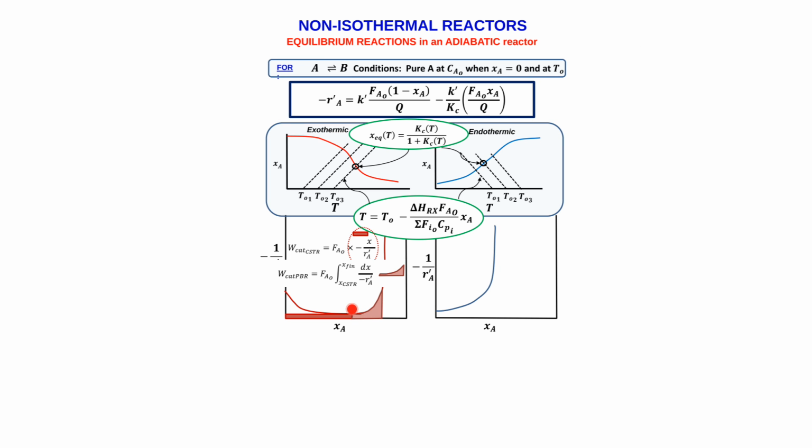So, of course, for an adiabatic reversible reaction rate expression, it's possible to see that there will definitely be a maximum in the rate. For that range, if you want to design this optimal reaction train, choose a CSTR followed by a PFR to complete the rest. And of course, the rest, meaning if you go to infinity, even though that is just going to follow that line, it's still going to result in an infinitely large area. So you will stop somewhere before you reach that equilibrium asymptote line.